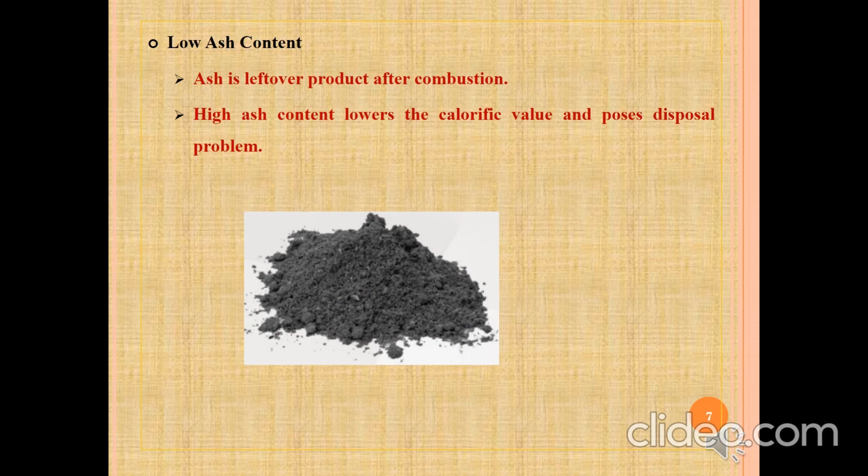The third point is low ash content. Ash is the leftover product after combustion of fuel, also known as non-combustible substance. Solid fuel having high ash content lowers the calorific value and poses a disposal problem. Lower ash content or no ash content definitely increases the efficiency of the fuel. So for a good fuel, the ash content should be very minimal.